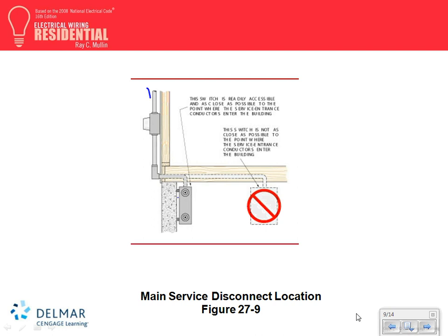Here's my conductors coming in here. They enter the building. Now, Spencer, I have to put my panel right at the point where it enters the building. If I can't, with special permission, I can put it in an inside wall. I think in Wisconsin, don't they have the 8-foot rule? They don't want you from the point you enter over here to the point where you put your panel or service entrance to be more than 6 feet. That's Wisconsin. In Minnesota, the nearest point of entry.